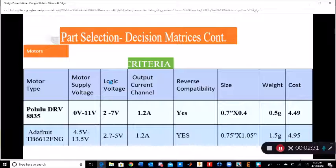And the most important one is the supply voltage. The one we chose operates from 0 to 11 volts supply, while the other one operates from about 4.5 to about 14 volts. So we chose the first one because we are using the LiPo battery.